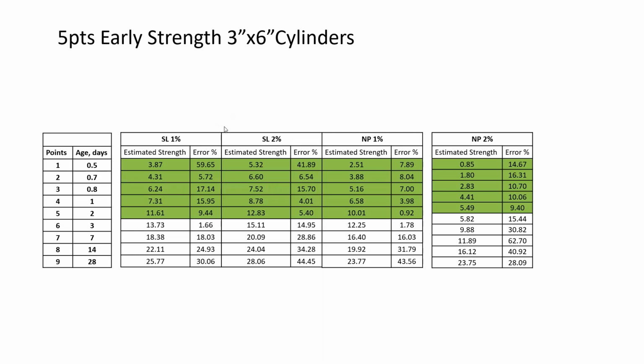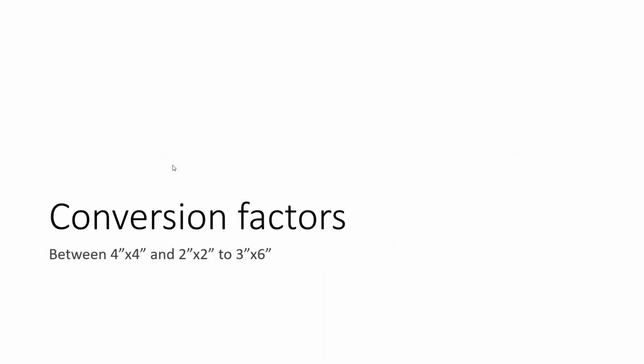that we looked at the error in the estimation, in the prediction. So every time you see this error, it's the error in the prediction of the strengths when you use the developed maturity based on certain assumptions. And we are assessing these assumptions to come up with a set of good recommendations at the end of the day. So that's one thing we looked at, the errors and the sensitivity to the breaking points.